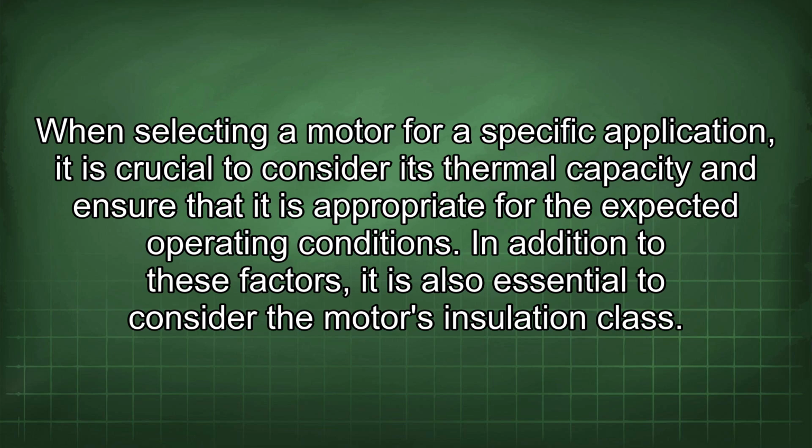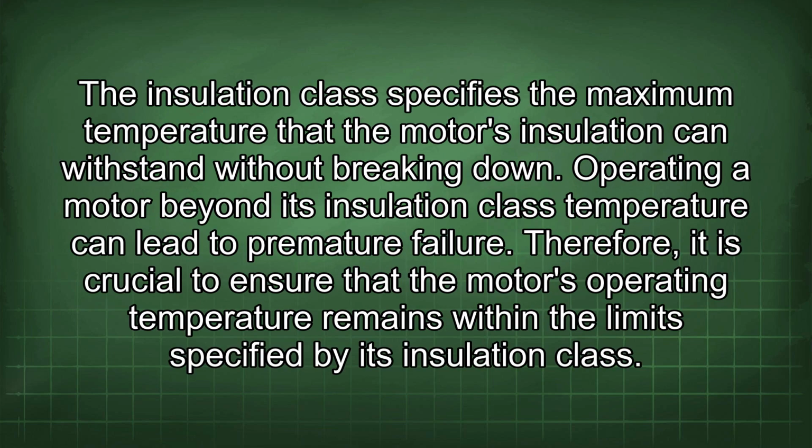In addition to these factors, it is also essential to consider the motor's insulation class. The insulation class specifies the maximum temperature that the motor's insulation can withstand without breaking down. Operating a motor beyond its insulation class temperature can lead to premature failure.